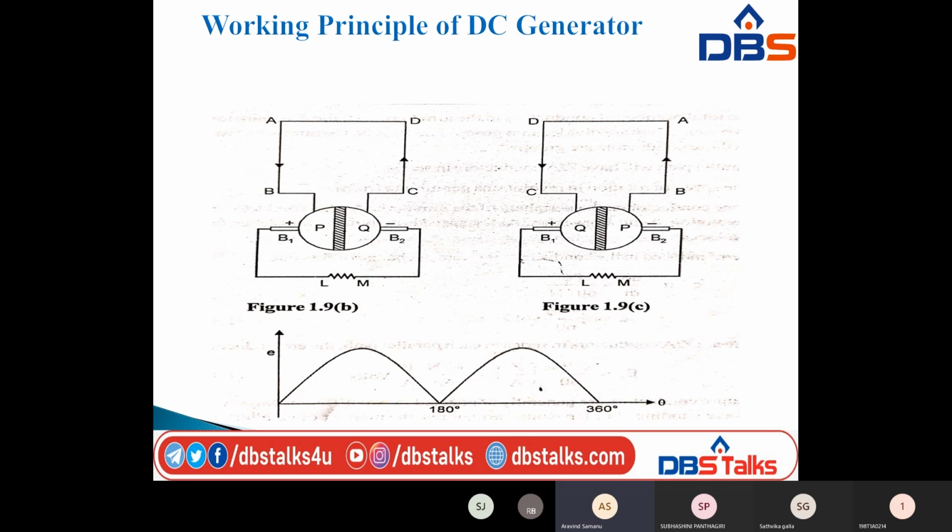The current flows from AB to the brush, comes to the external load L and M, goes to brush 2 and then into CD. That is, the current flows along AB, LM and CD, through brush B1 which is positive and into B2 that is negative.